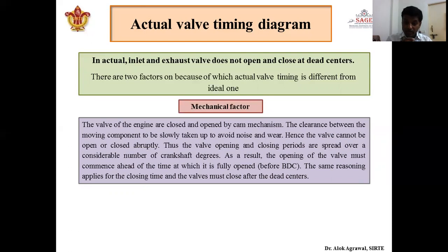If the valve has to be open completely at the suction stroke, then we have to start the opening of the inlet valve before the piston reaches top dead center. It means when the piston is about to reach top dead center, before that only we have to start the process of opening the inlet valve.